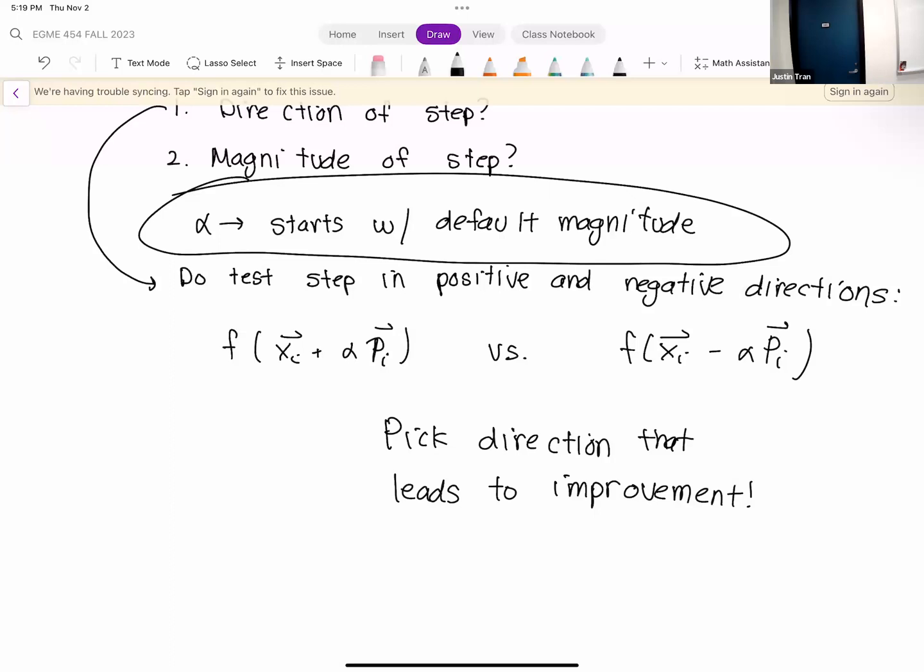Okay. But I did notice that if I increase the iterations, I do get a different value. Doesn't that just mean I'm looking at more directions? Yes, it's just taking more steps. This algorithm stops when the step size reaches the minimum step. So you can either slow that down by not dividing by 2, or you can increase this to force it to take more steps. They both end up with the same effect. Was the value of size 500 not the optimum then?